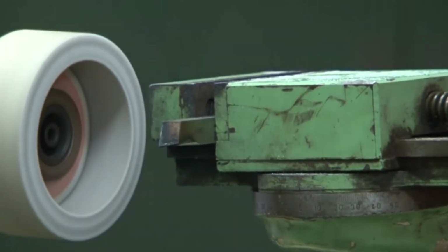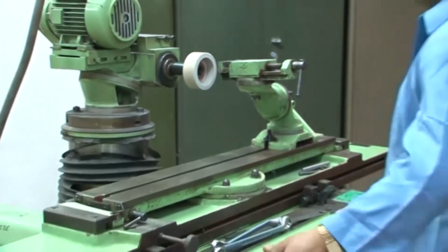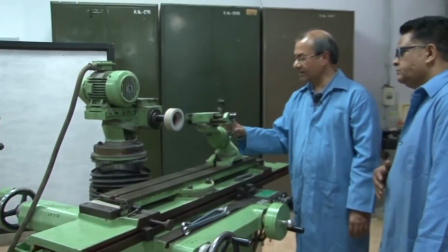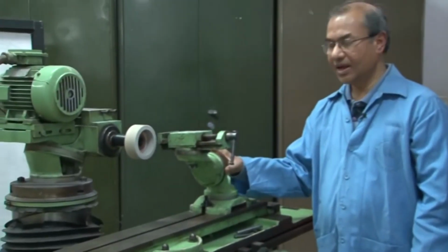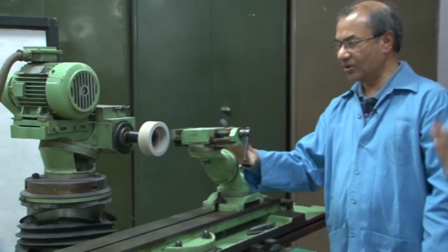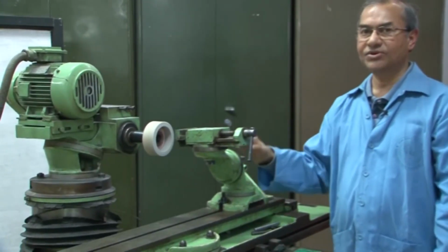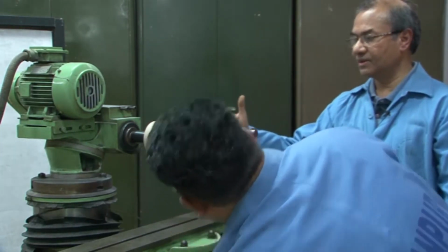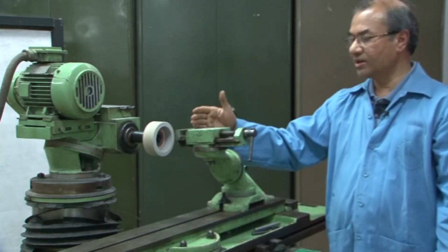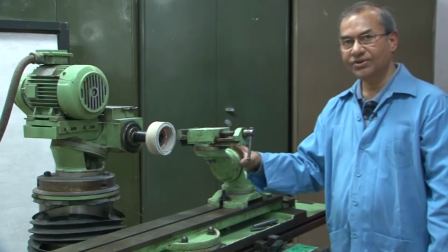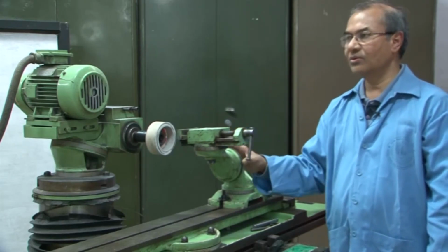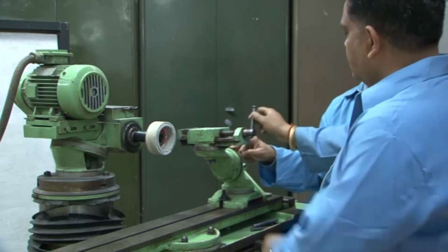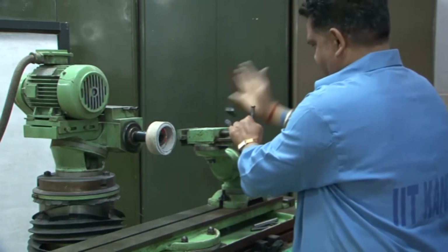And that angle that you require, as I was telling, the tool has to be set very carefully. This angle is selected by this dial. This dial is graduated and it can be rotated, so that according to the angle which you require, that angle can be given here. So, it is not simply mounting the tool, but mounting the tool at a certain angle at which the side rake angle that you want to regrind can be established. So, this is important. As I said, that angle cannot be an arbitrary angle.